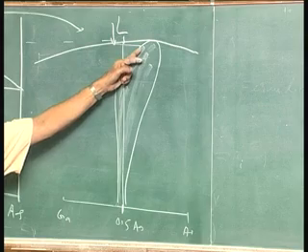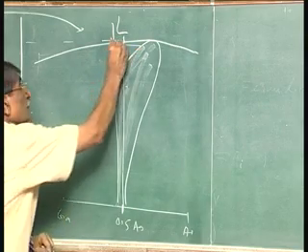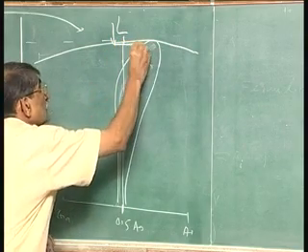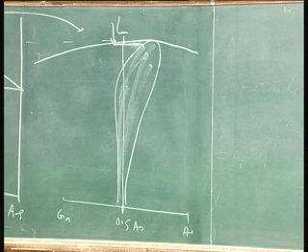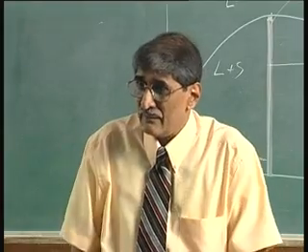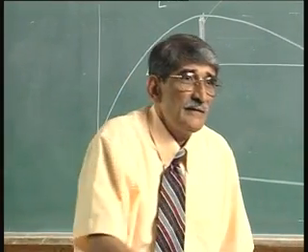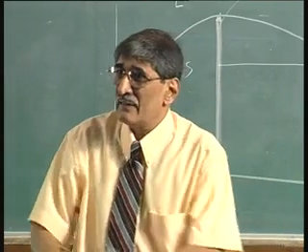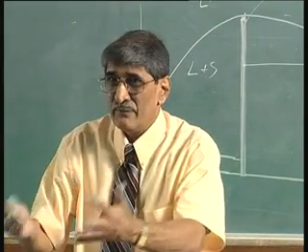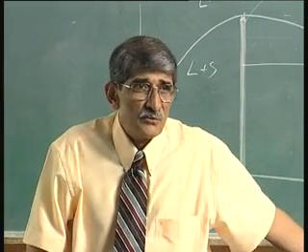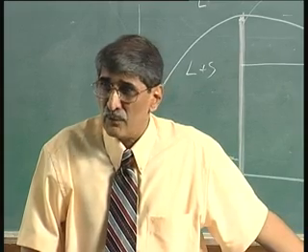That is the meaning of the phase diagram. So if I have the composition corresponding to this, that is slightly arsenic rich, you have excess arsenic and also gallium vacancies. Those excess arsenic atoms go and sit in the gallium site, which is the anti-site, and which becomes beneficial for you to compensate for those carbon or boron impurities.